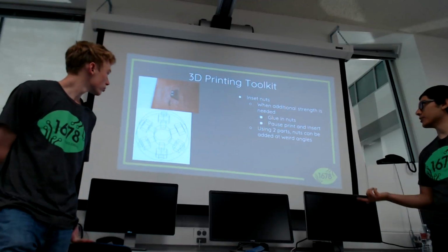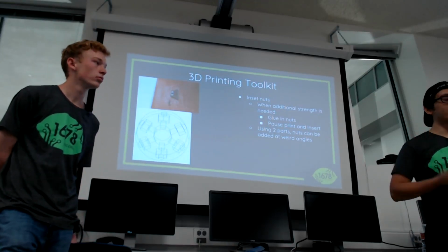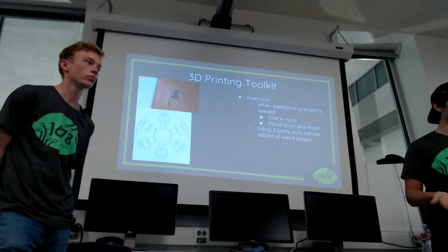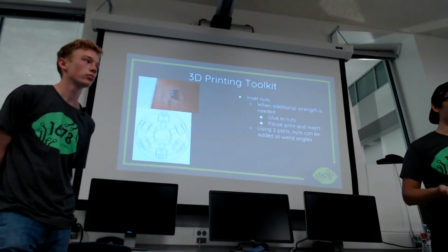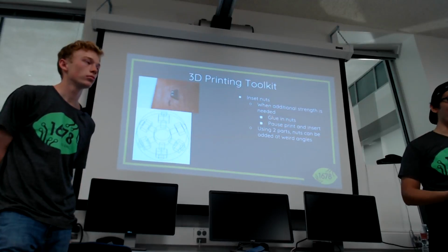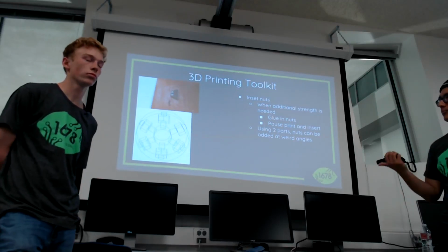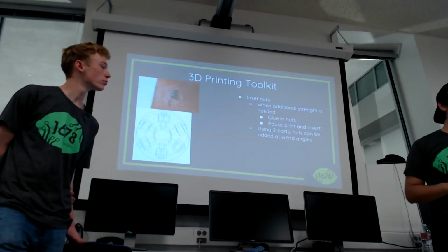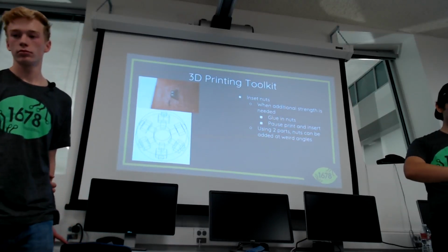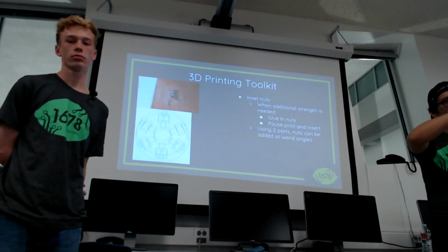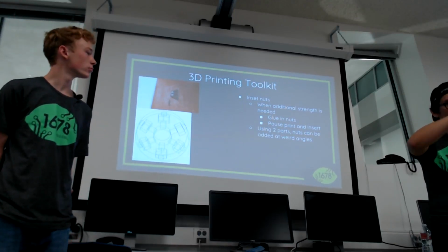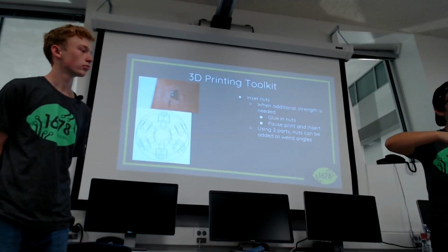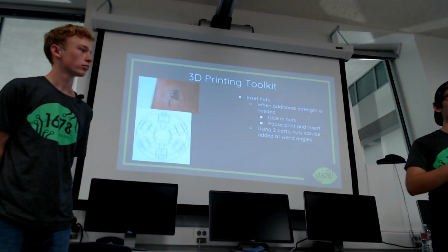A couple of tips when doing that: use super glue, because it helps to keep the nut in place if it happens to become dislodged when the part is complete. Then there's no way of recovering that. The super glue helps not only by retaining it in place, but it stops it from rotating in shear along the face, by providing a shear force along the face of the flat sides of the nut, and that kind of helps the material stop from deforming.